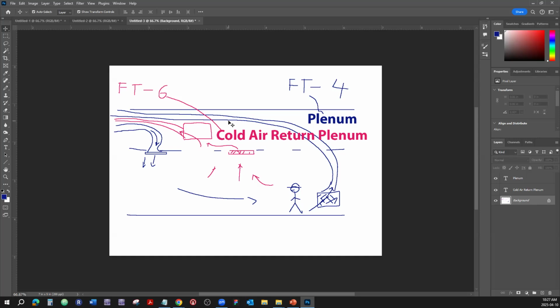And if it's FT6 or FT4, it is still, as far as the data transfer specifications, no different. The only difference is the jacketing that is being used, and FT4 burns quicker, releasing toxic fumes.